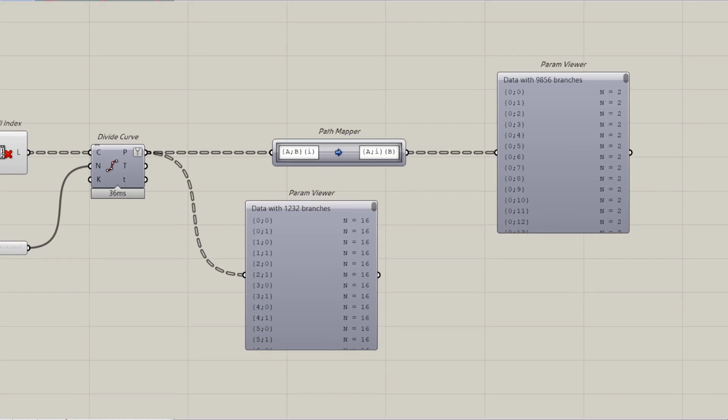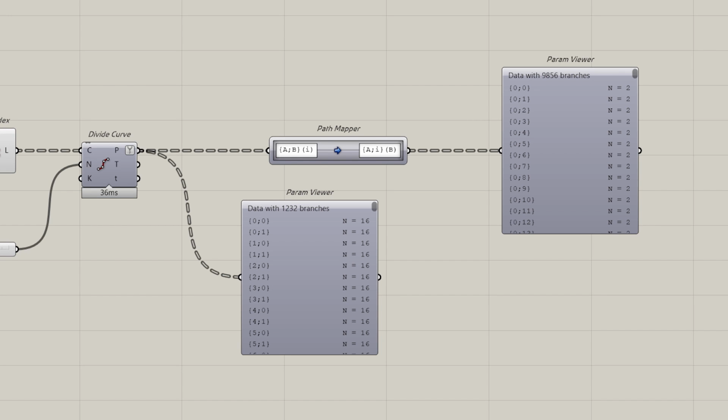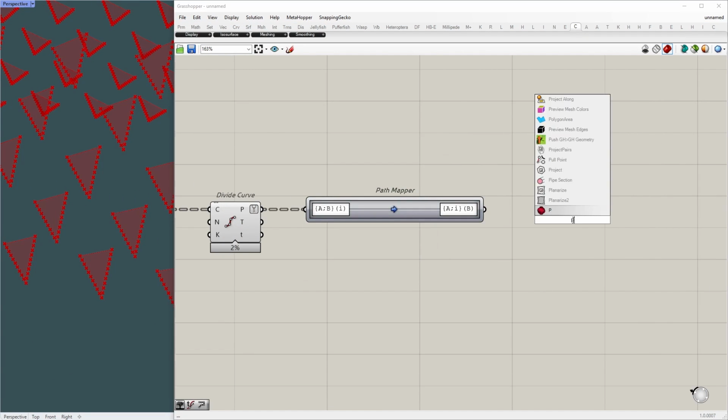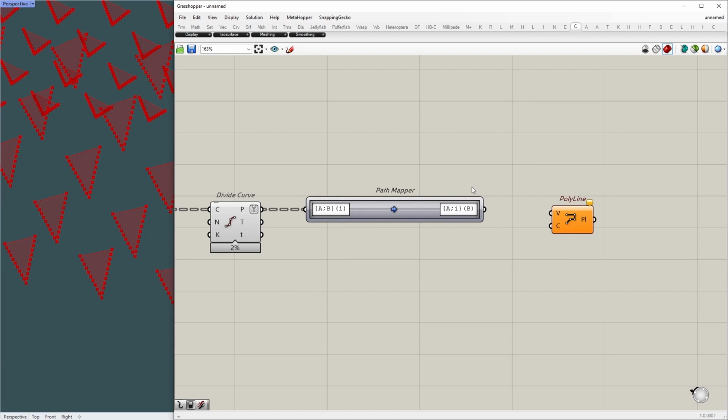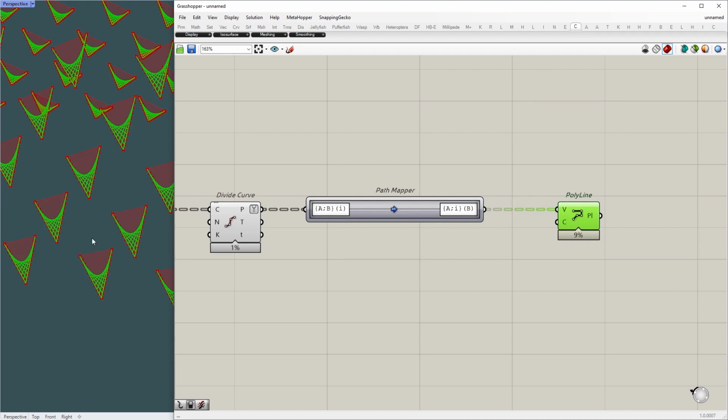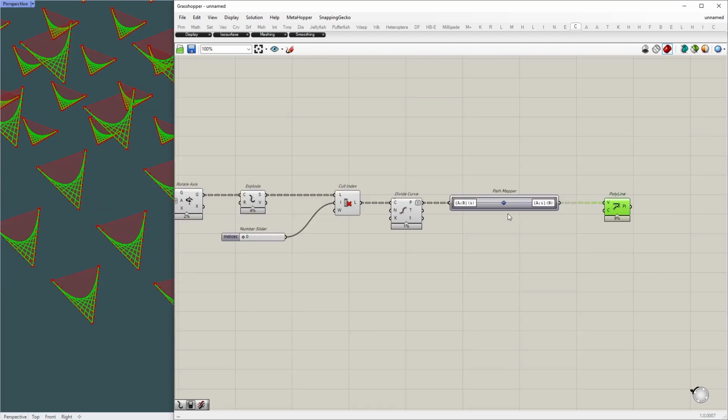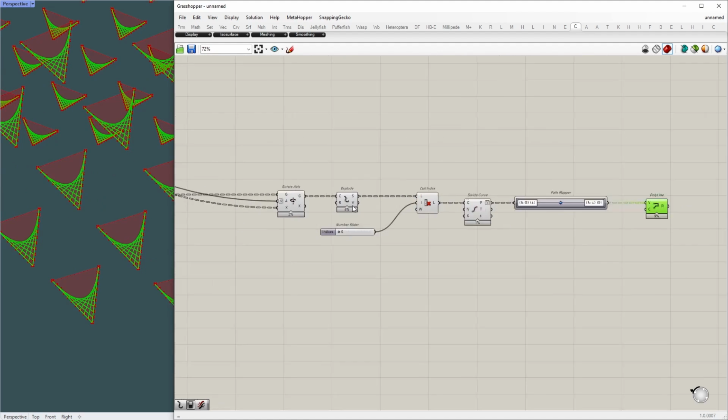Here flip the last branch with its item. This makes 2 points in one branch. By using polyline nodes, we can easily make lines between them. Now the curve is crossing over. To fix this, we can flip the curve direction on one of the edges.